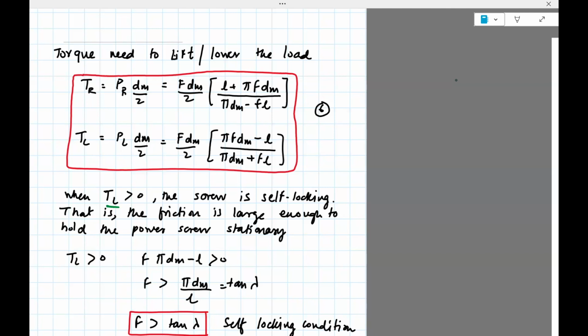It's not applying a load to get the jack back. It's because it's self-locking. It's not going to basically move. So there's a condition which prevents the load from going. You lifted the car up, and now the car will not move down. The whole system needs to be self-locked. Otherwise, you're going to sit there and apply a force to keep it up.